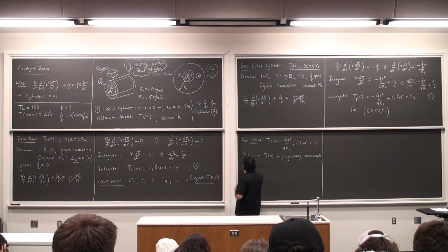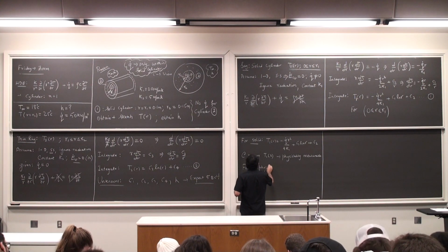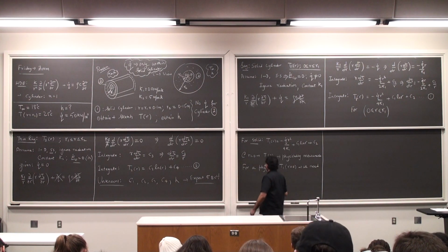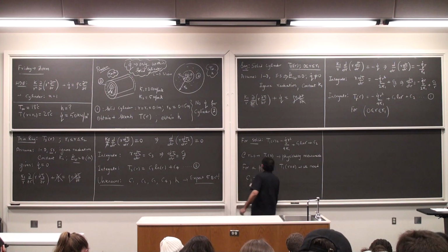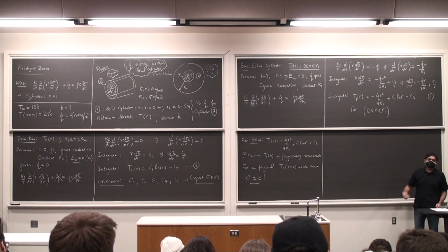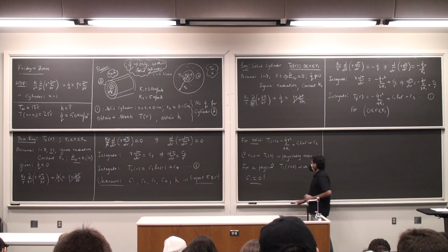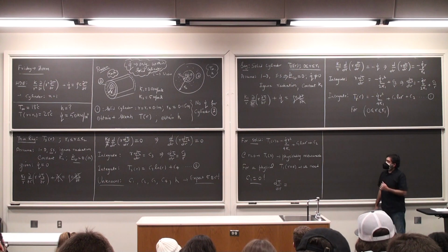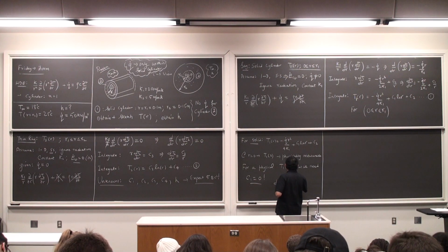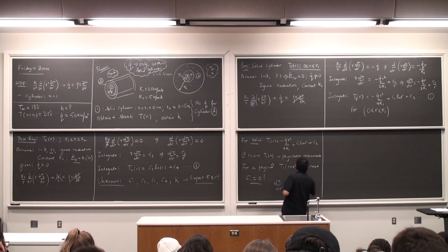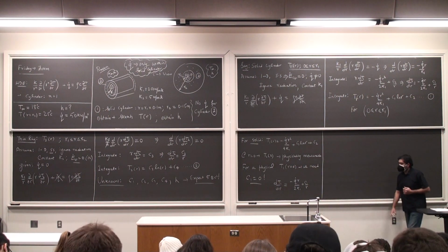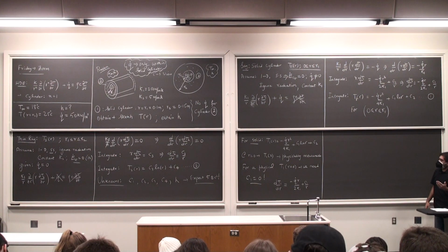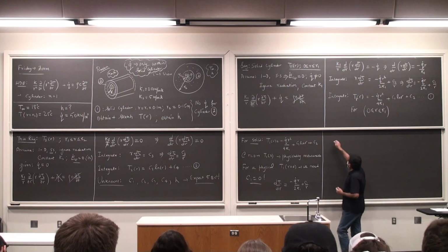So for a physical answer, T1 at R is equal to 0, we need C1 is equal to 0, and this is equivalent to saying that for a solid cylinder, if I take the first derivative, this is minus Q dot R by 2 K1 plus C1 by R, and C1 is 0, and at R is equal to 0, we will see that the slope is 0. So solid cylinder only.